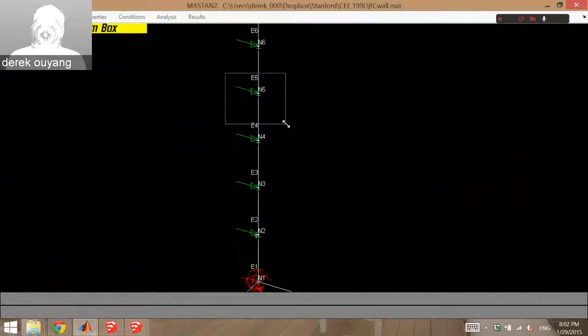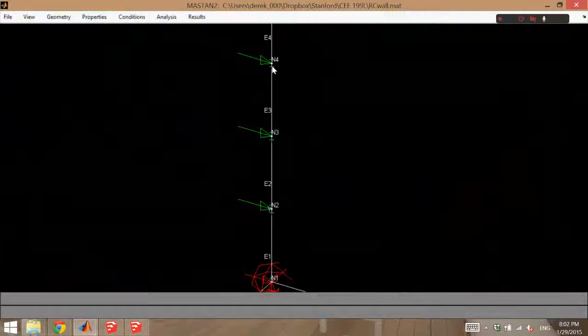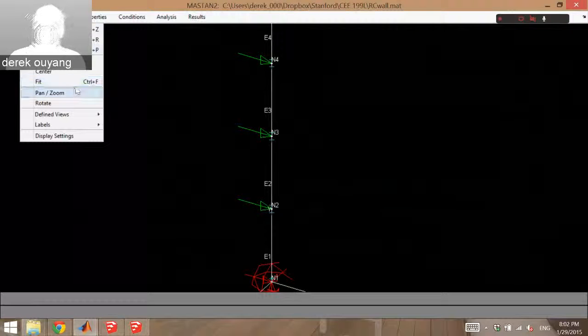I don't think it's going to be necessary for you guys, but what that's telling you is the warping constraint, so whether these are warping together. I will show you a very quick example of what happens if this shear wall is not directly in the center of the building. Then you're going to have to account for an additional force, right? So you can try to model that for your third one, but there is some math behind it that I don't think you learned as an undergrad.